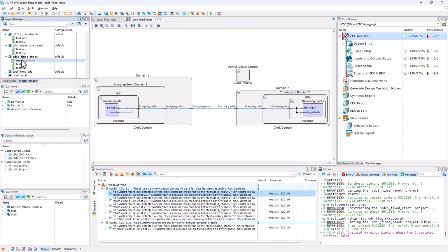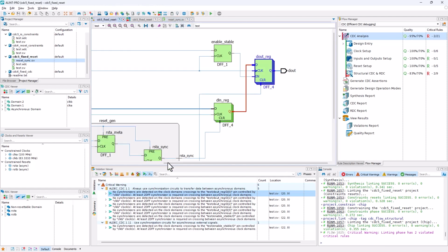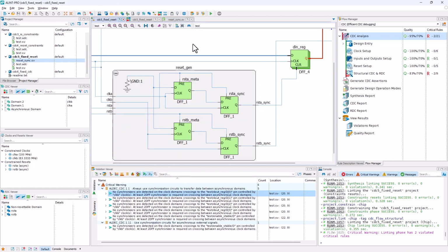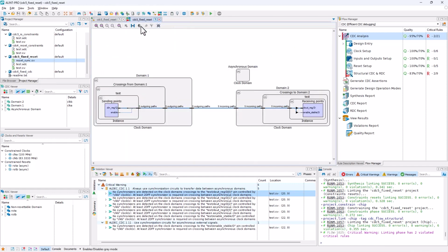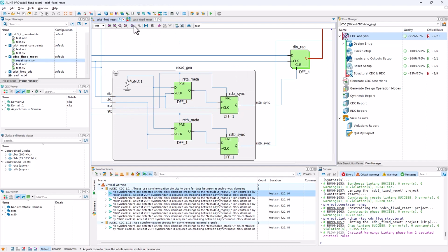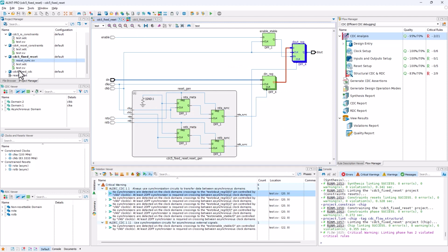And finally, we can also take a look at the reset synchronizer module and see how they made it. And again, this is what I described before in this diagram, where you see the two back-to-back D flip-flop synchronizers, and these are both of them there, one for clock A and one for clock B. So I'll go ahead and close out this tab. We'll keep this open as well as the view of our RTL, and we can use these to compare when we switch over to CDC6.